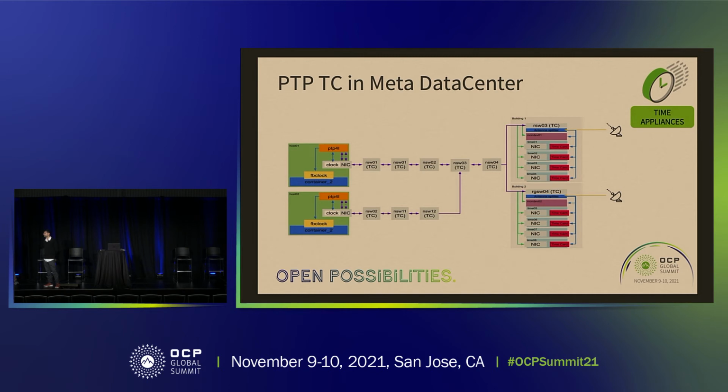PTP master clock, keep doing the good job, no problem. Even the physical layer, let's say SyncE, still working fine. The most important factor is to assume that a disaster situation happened and you lost it all. In that kind of case, that's why the oscillator's holdover accuracy matters.